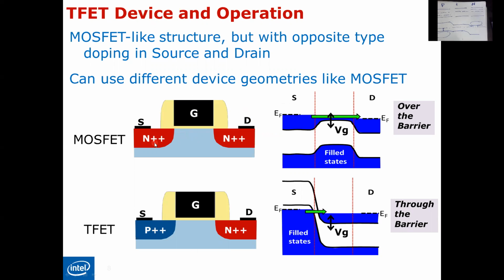This is the ordinary MOSFET, where, as you mentioned, you have the source and the drain, both of the same type of doping, and you have a substrate with a different type. Herein we have a source which is a P, a drain which is an N, and what is in between is intrinsic. This is an energy band diagram for the cross-sectional area for that NPN junction in the MOSFET.